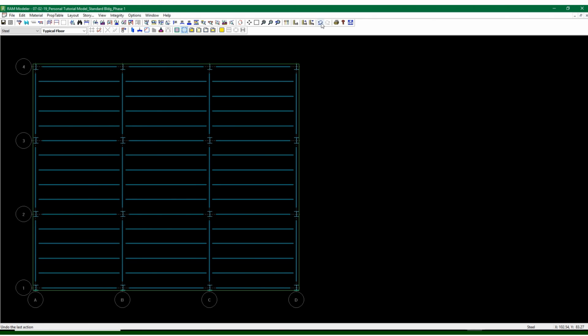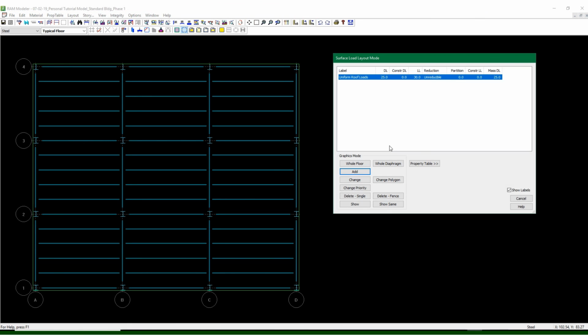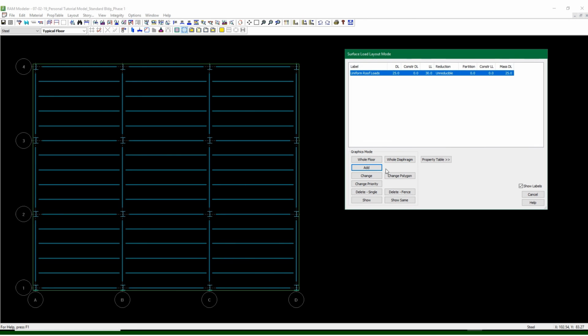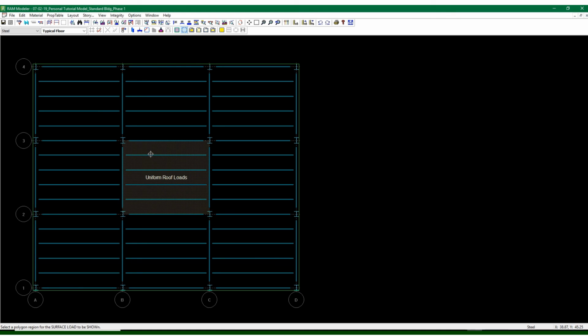So it's okay. I could undo that, but I don't know what's been undone. I could just undo it some more to be on the safe side. I come over here and I still don't know whether or not it's been undone because the loads are not shown graphically. So here I have to select the loads and say show loads, and it shows the first one. I clicked on the undo button 2 times, so the last two area loads went away, but not the beginning.